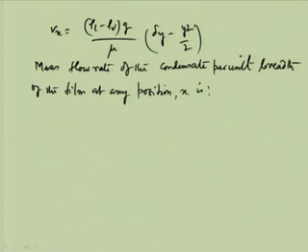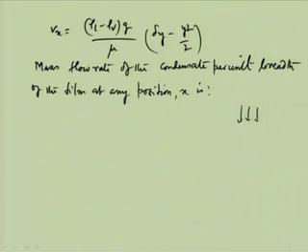It is nothing but velocity into the area. The film is coming down like this. We know the velocity Vx, and we know the surface area. This gives the volumetric flow rate, and then multiplying by rho gives the mass flow rate.